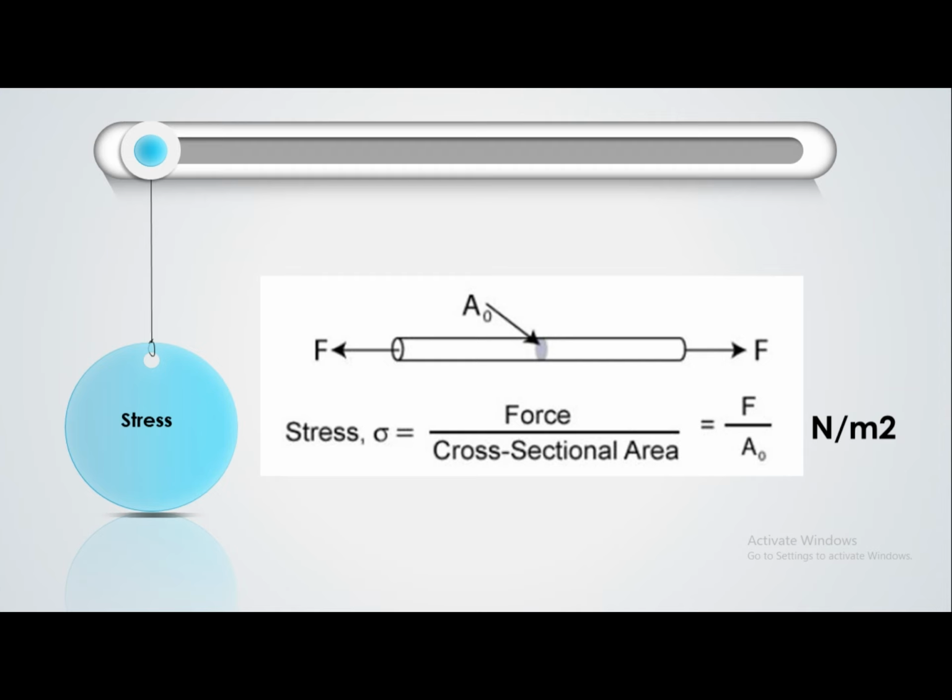Number two is, what is the stress-strain curve? Firstly, the term stress is used to express the loading in terms of force applied to a certain cross-section area of an object. From the perspective of loading, stress is the applied force or system of forces that tends to deform a body. For example, a bar loaded in pure tension will essentially have a uniform tensile stress distribution. The stress in an axially loaded bar is simply equal to the applied force divided by the bar's cross-section area. The stress can be measured in newtons per meter squared.